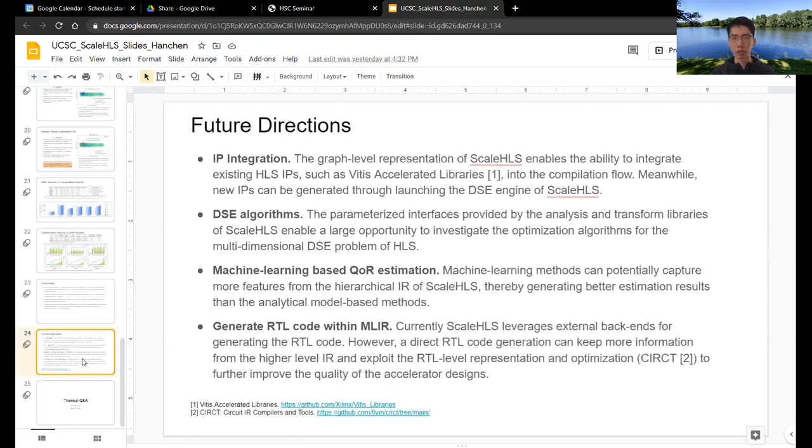If that is not resolved, or the distance between these dependencies is very short, this means you cannot achieve a very low initial interval. So we are using these two things to estimate the minimum initial interval you can achieve. And I think the estimation for the pipelining is the most difficult part of the estimation. Let me think about whether there's other things. I think that's it.